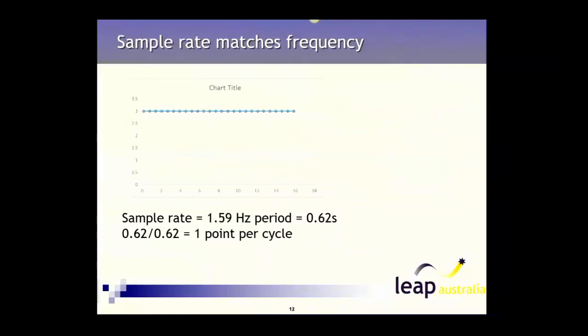And if we magically happen to use a sample rate that skips over the troughs, this will look like a flat response. So this means that if your time step is too big, you totally miss some frequencies in your response. Okay, and if they're quite dominant frequencies in your analysis, that means that although the solver will give you results, they may look quite believable, but they'll be totally wrong, because you've used a time step that's excluded a particular frequency.